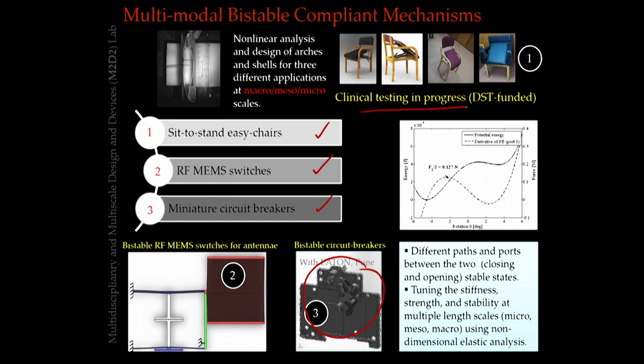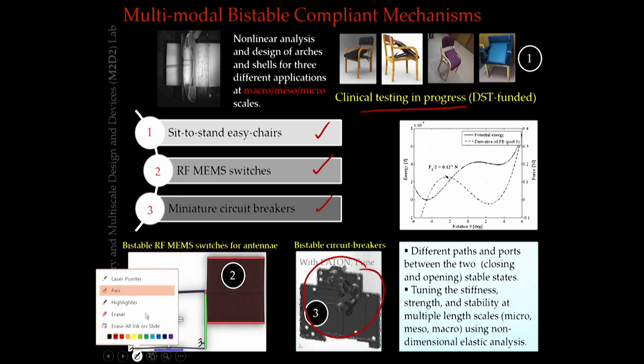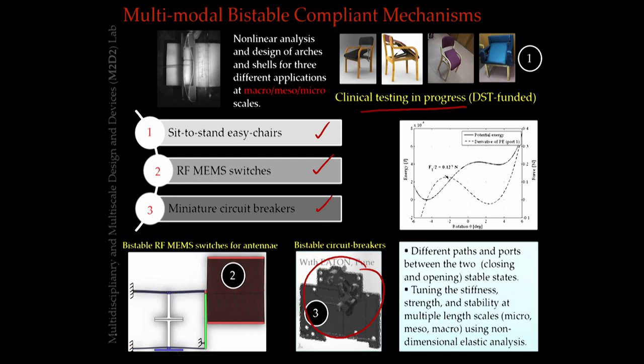And decreasing state energy for a compliant mechanism is advantageous from the viewpoint of mechanical advantage also, as we had discussed earlier. So, bistable devices inherently have this non-linearity which we exploit to get this feature of having one stable state and another stable state, and in between they will be unstable.